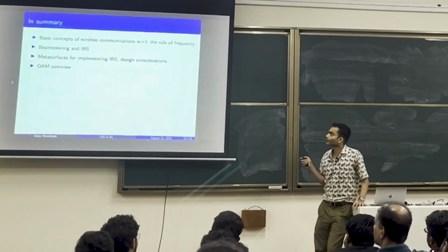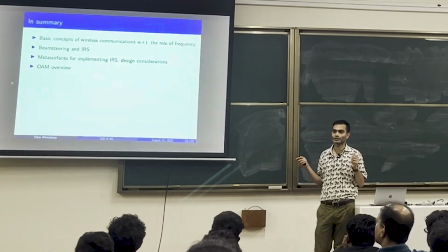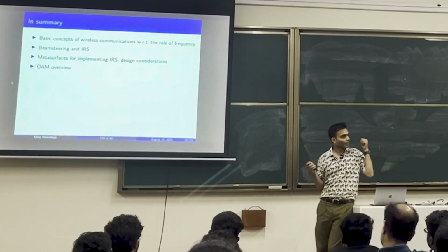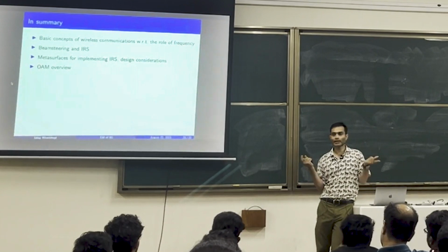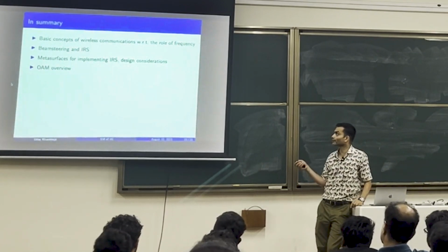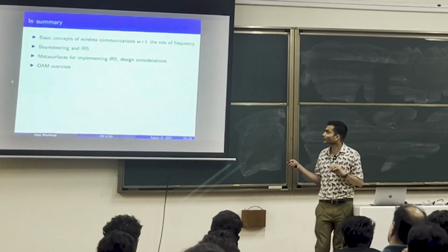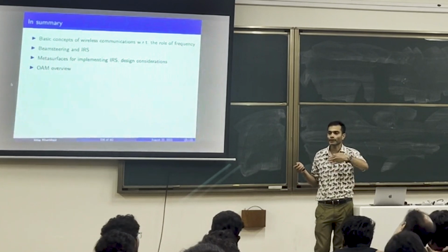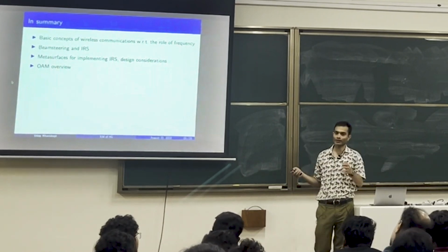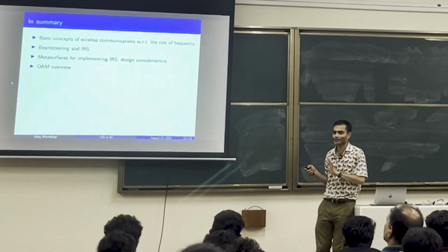We've looked at, I mean, this is absolutely fundamental, right? What is the role of carrier frequency? It influences data rate, it influences coverage in opposite ways. So, we found out that to get over the coverage problem, we need these reconfigurable intelligent surfaces. Why are they called intelligent? Simply because they can dynamically change their phase depending on where the user is. That's all that there is, no ML happening over here. Okay, it's intelligent in that sense.